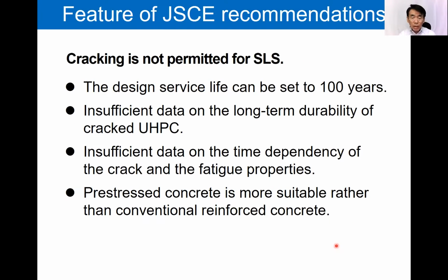The next is cracking is not permitted for the serviceability limit state. You may think this provision is very conservative. Of course, we know that this material is very durable compared with normal concrete. However, the recommendations state that we can set the design service life to 100 years using the standard material.